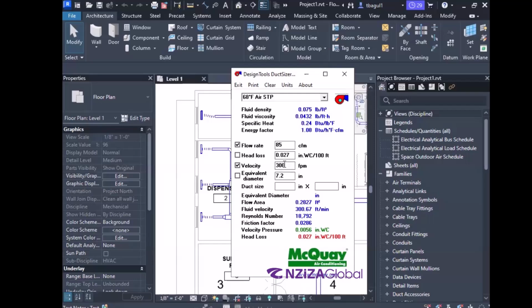We spoke about the different types of HVAC systems, right? The noise criteria when we had a dual duct connection was a matter of concern. Why? Because there are different components that the air is passing through, double components, on the hot side and the cold side. That is the reason why we try to restrict the air velocity to as low as possible.